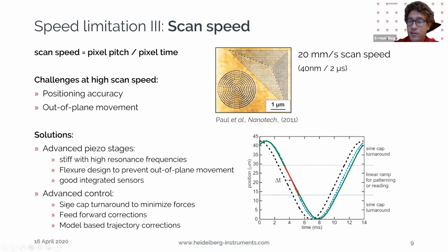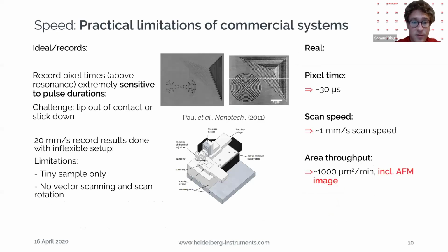We have special actuation of the turnaround. We optimize the turnaround, and we also use feed-forward corrections and a model-based trajectory to optimize the whole trajectory during operation, to minimize the out-of-plane movements and optimize the positioning accuracy. And that's very interesting.